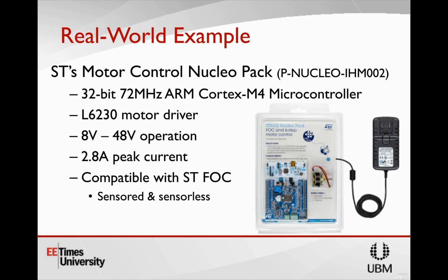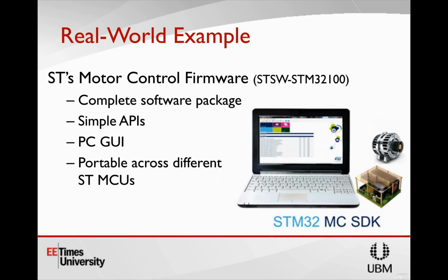So if we take a look at some of the motor control firmware available from ST, it's really a complete software package that features simple APIs, a PC GUI, and it's portable across all the different ST MCUs. And this does implement field-oriented control, both sensored and sensorless. It also includes some advanced functionality, such as the HFI, the high frequency injection initial position detection that we talked about earlier.